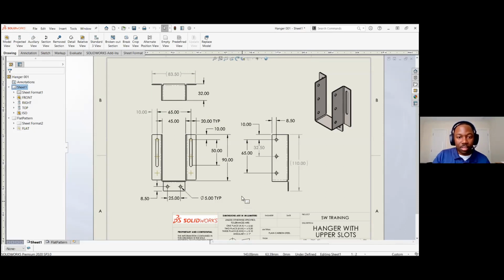And then Danny's asking about the detailing mode. Detailing mode, it's still an SLD DRW. There's not a different file type you need to save it as. A lot of times when people send you an assembly, they don't send you the part files. You can send somebody just the drawing file and open it in detailing mode. Right, guys? You don't have to have all the parts. They just have to be saved in 2020 format. Yeah. That's it. And I forget, I don't have the detailed listing in my mind, but it's very similar to the detached drawing that you could have. I think there's just some more functionality there if you open it in detailing mode.